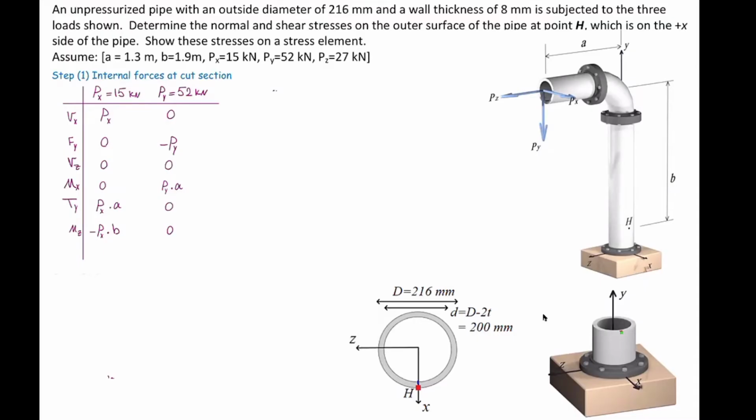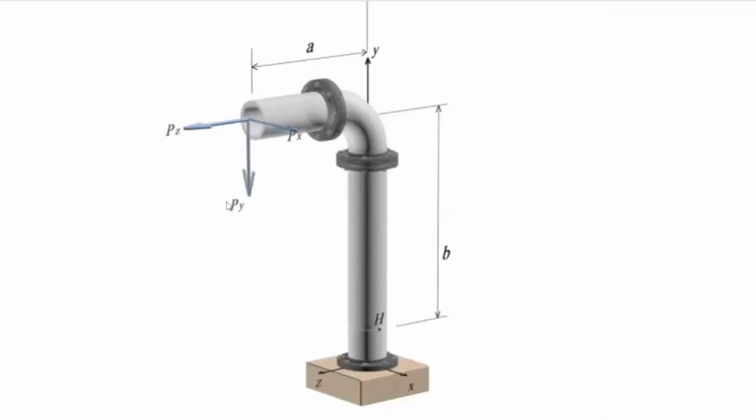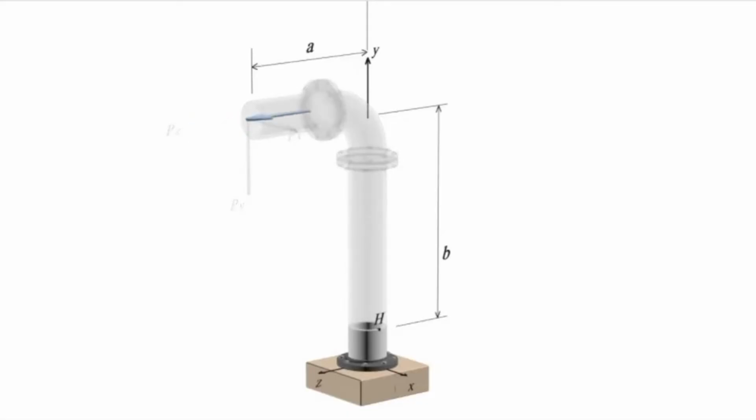All right? Now let's do that for the very last force, force Pz. Now we are getting rid of all other forces, and we just focus on Pz. The first move is not producing any extra moment because we are moving the force along its own direction. The second move, however, would produce extra moment. The magnitude of the moment would be equal to force multiplied by the distance, which is b, so that would be Pz multiplied by b, and the direction is determined using the right-hand rule.